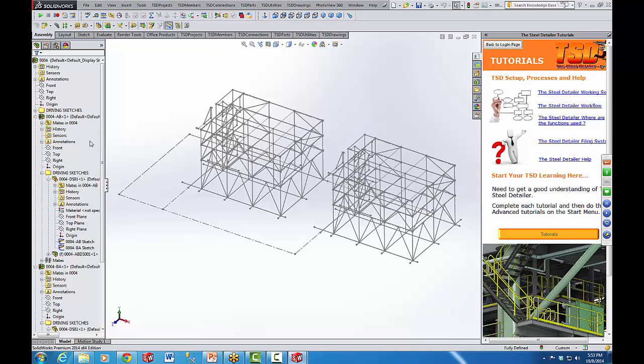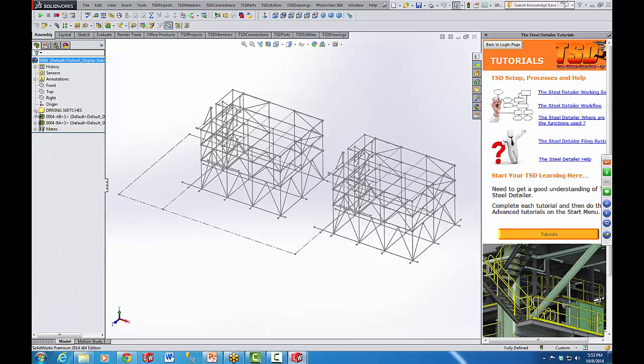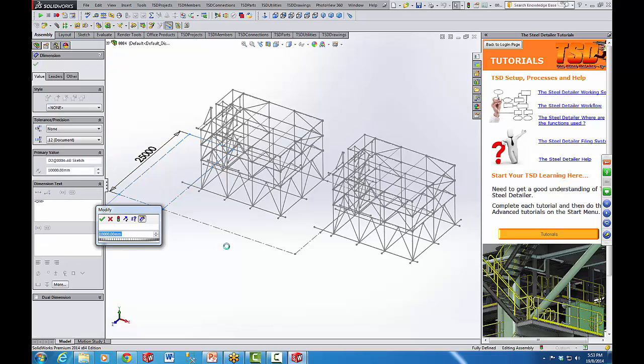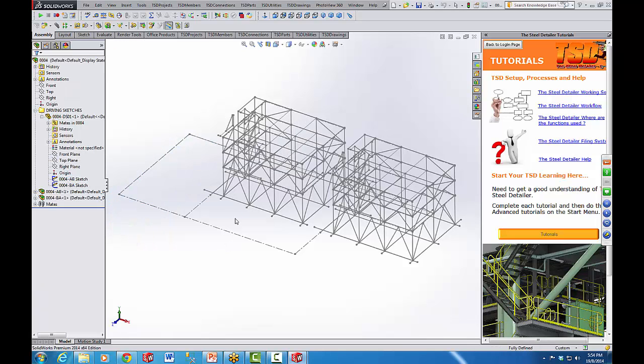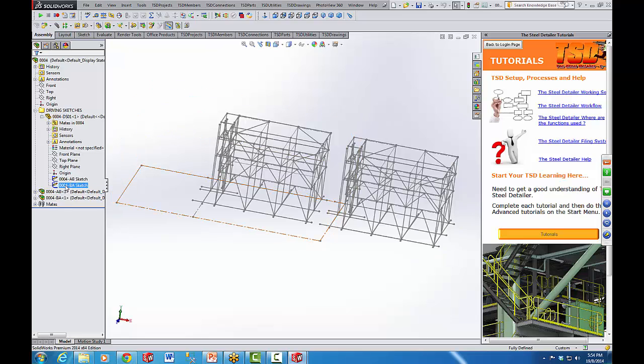It only moves at the top level area. So you can see how this works if we go into the top level driving sketch and change it just by simply double clicking on the sketch, and if we go say 15 meters, you'll see that that one sketch has just changed in its position. So this is used to drive its position on top of one another. This is used for really large assemblies, and when you're overlaying one area with another to create GAs for that area, we use this process.